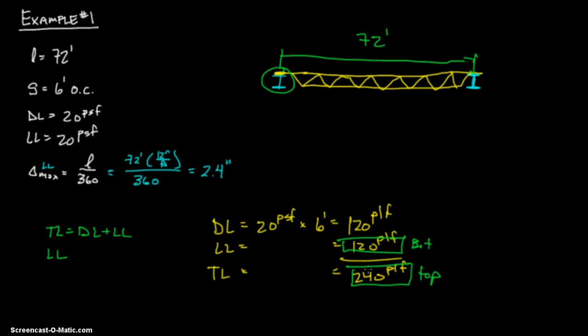And you go down, 209. 240 is bigger than 209, but it is less than 267. And we go to there, and we also look at the live load, and it is less, so we'll circle that, and that means that's good.